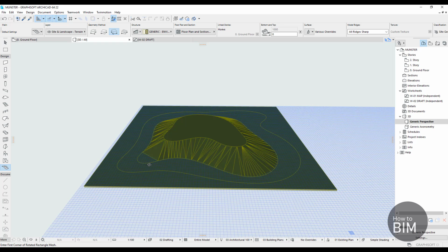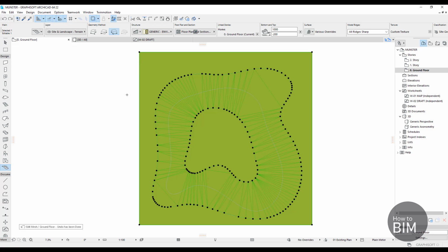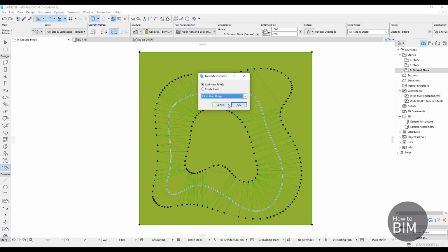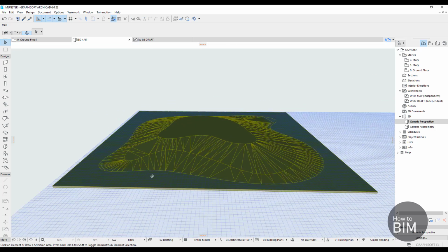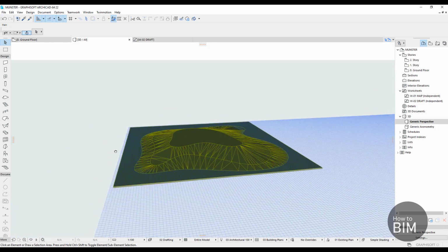As you can see, if I select No Surface Fitting, it will only start at the 0, 0. So that means that if I have this on 0, 0 and this on 0, 0, then this is actually still not a hill, but a plane, and only from here my hill is going to start. But I want to have also this, so okay. So this is how we create a hill in Archicad.